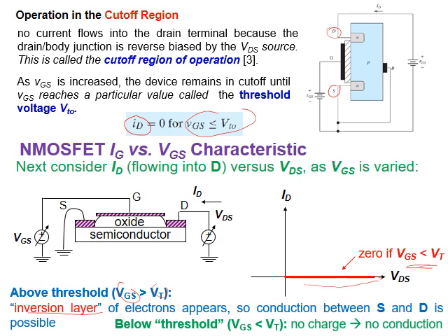For that we call it field effect transistor. It works on the effect of the field which makes this transistor work. It makes a field of electrons layer called inversion layer. This field of electrons will be like a conduction between drain and source, controlling the flow of current between drain and source. Let me show you.